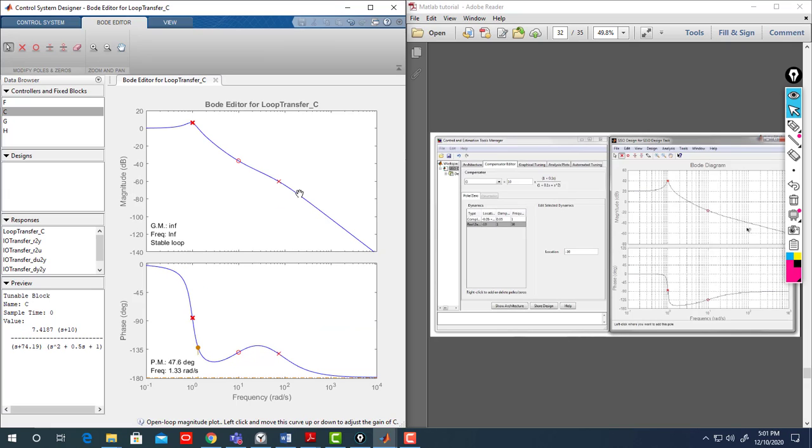See, this will go to minus 40 decibel per decade again, similar to the first one, because it was a second order system; here you have two complex conjugate poles. And here it returns to minus 180.